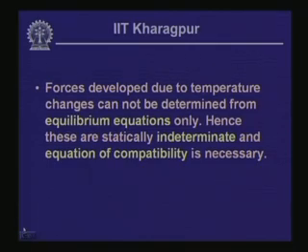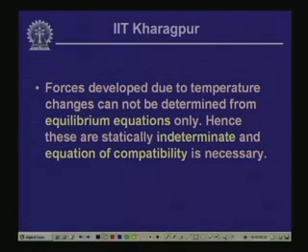So, forces developed due to temperature changes cannot be determined from equilibrium equations only, and thereby these particular kind of systems are statically indeterminate, where there is a change in the temperature in the system. When we evaluate the forces because of that, or when we evaluate the thermal stresses due to change in temperature, the system is statically indeterminate, and we need the help of compatibility equations, so that we can solve the stresses due to temperature change.